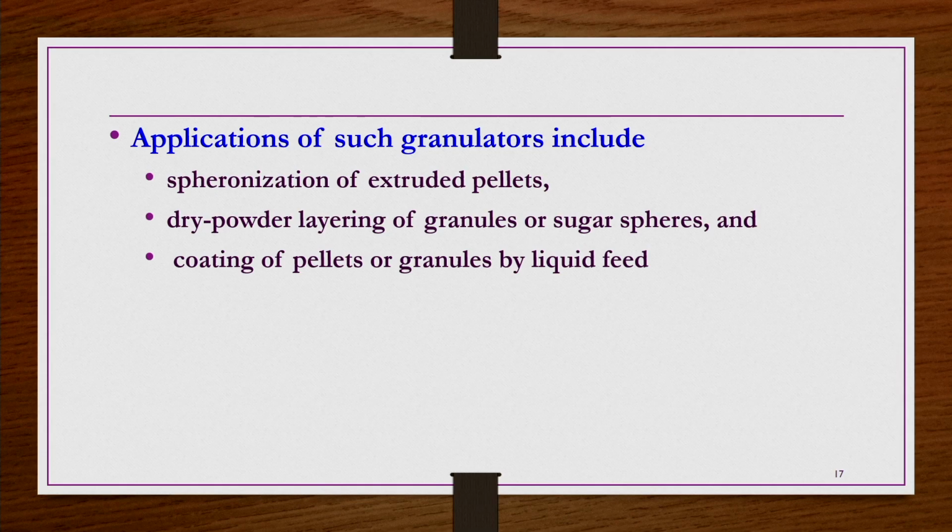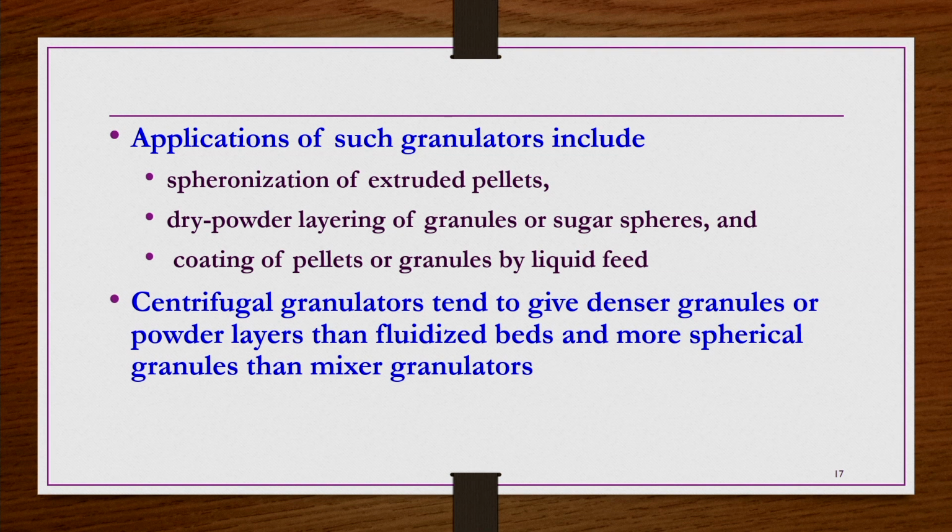They generally have applications in spheronization of extruded pellets, dry powder layering of granules or sugar spheres, and coating of pellets or granules by liquid feed. Centrifugal granulators tend to give denser granules or powder layers than fluidized beds and more spherical granules than mixer granulators.